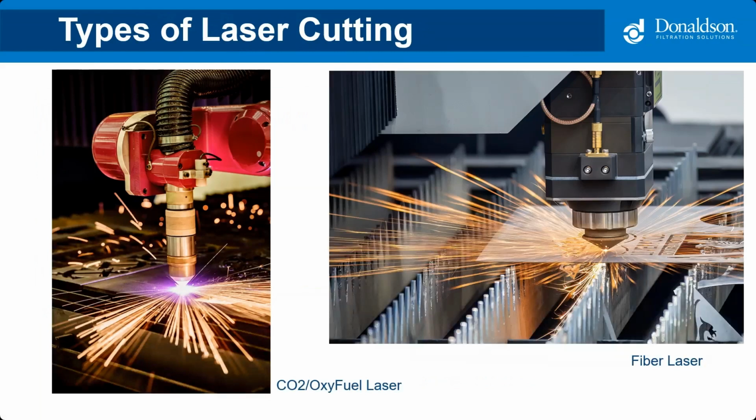The two most common laser cutting systems are CO2 and fiber. Fiber lasers offer advantages over CO2 lasers, particularly when cutting metals due to their higher efficiency and speed, especially with thin materials. CO2 or oxy-fuel lasers, on the other hand, are more versatile in cutting non-metallic materials and can handle thicker materials. It's also an important distinction when sizing a collector.